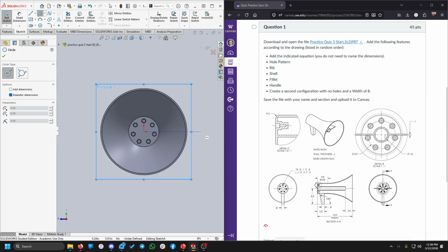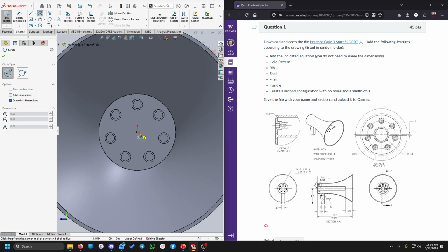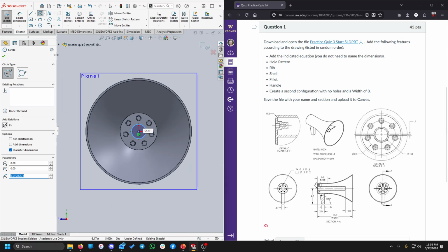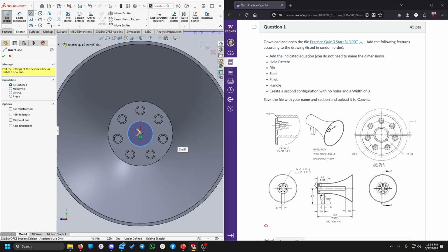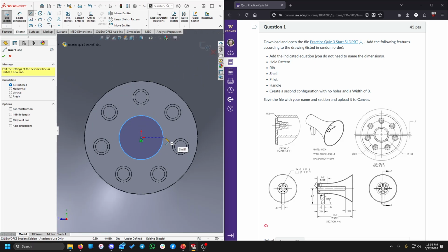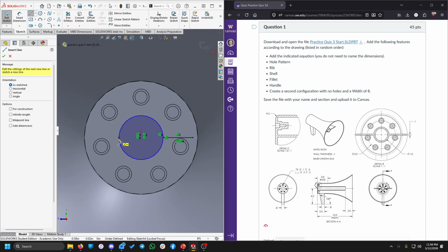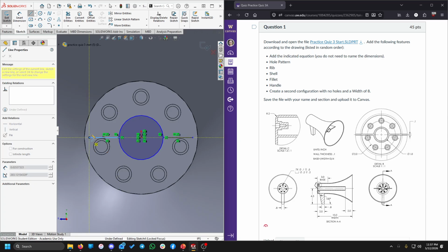And we see that for our rib, we've got this circle in the middle, and then it's got these wings sort of going out to the sides. So we'll do the circle centered in the same central location there. We've only got the 1 center mark, and we've got a couple of circles, so that tells us that all 3 of these are going to need to be concentric with each other. And then we've got the wings for our rib, they just seem like they go straight out from the sides. So we've got one, and we've got the other.